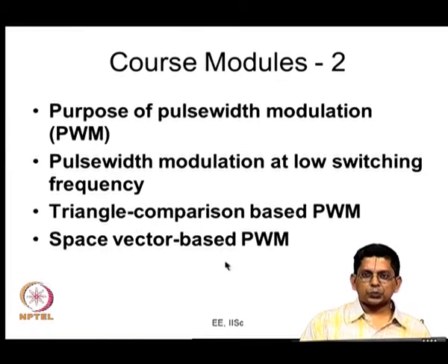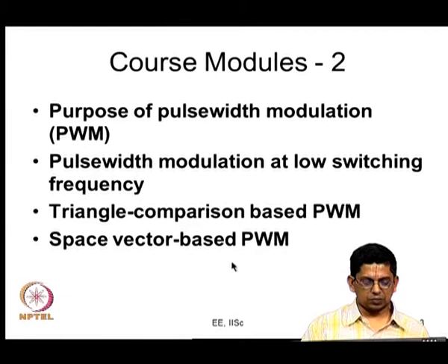But in space vector based PWM, we not only do that, we also divide the active vector time. It is also possible to apply an active state more than once, so the so-called division of active vector time could be done. The advanced bus clamping PWM methods do that: they apply only one zero state, but they apply one of the active states twice, and they produce some interesting waveforms, and they are capable of improving the performance, particularly at high modulation indices.